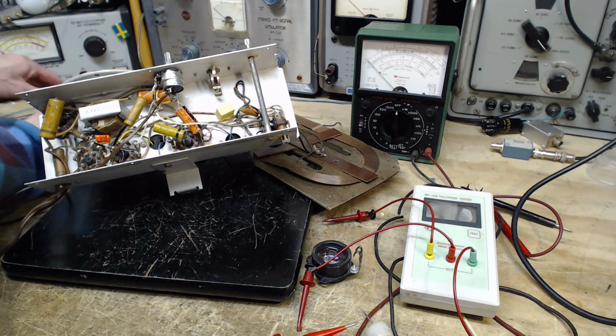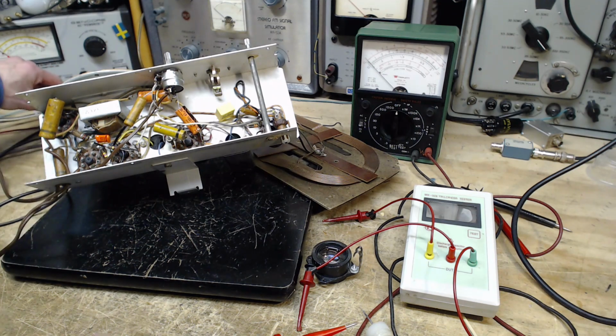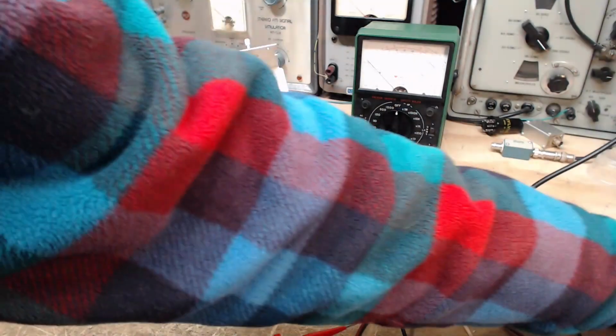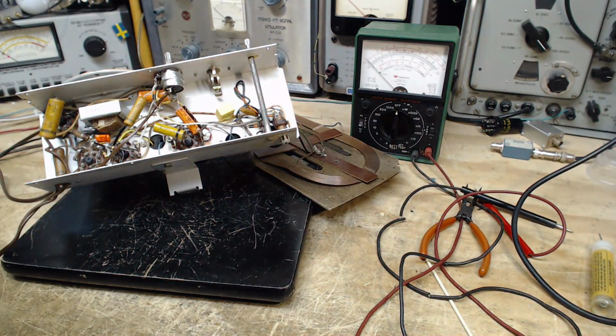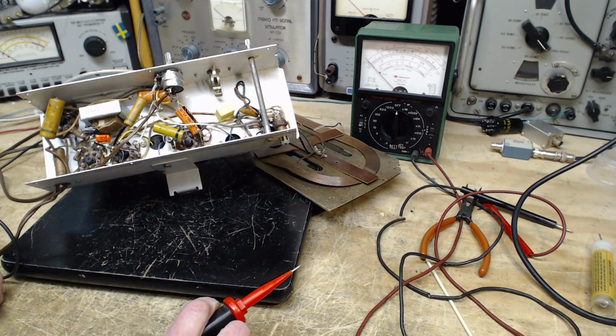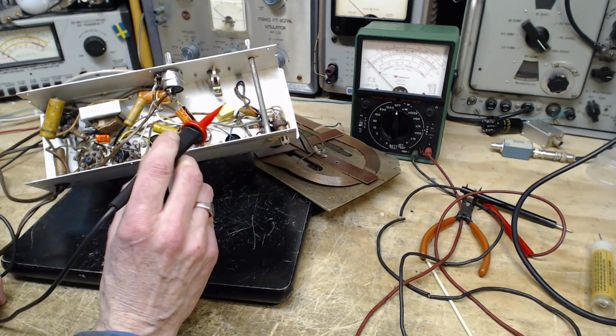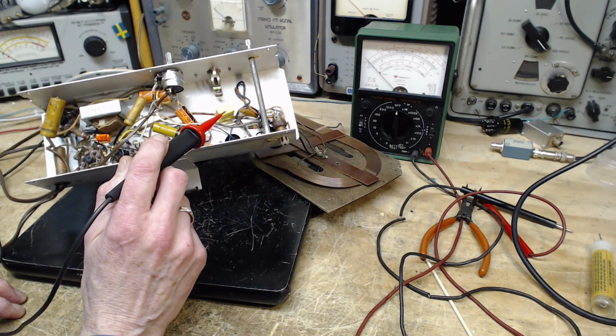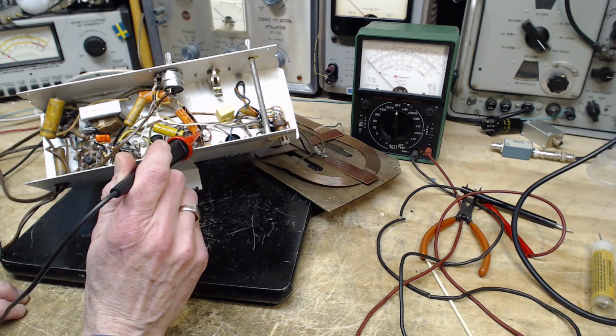So plug the radio in. Once again, don't know that I plugged it in the same way, but I think I did last time. Get some stuff off the bench here. Okay. So what's the story now? If there is current leaking onto the chassis, which we believe there is from some unknown location, that tiny current will encounter this capacitor. It's AC current, 60 cycle AC current, and it'll flow through this capacitor to ground. That's one way of looking at it.